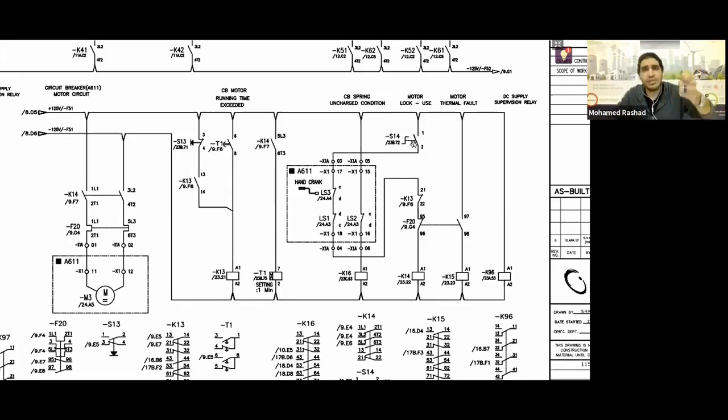So if you set the use position, chose selectors, and then set the use position, then came here and closed the box or the cover box for the manual charging of the spring, in addition to the spring being uncharged or discharged, this contact will also be closed. It will pass the positive. Like this, pass the positive, like this, and find two things here, leave them.